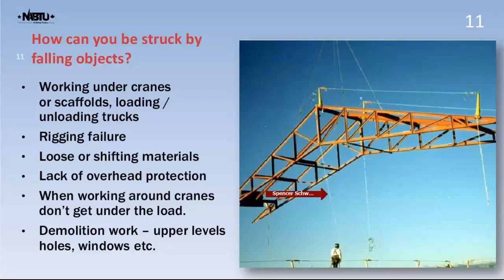And stuff can fall off of this equipment as it's being picked up as well. So you just don't want to work under the load. Also, demolition work. Demolition work is where they're tearing down a building, or part of a building, a floor. A lot of times people will pitch stuff out windows or wall openings.